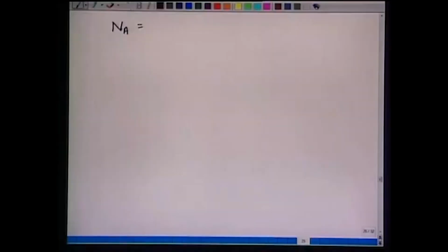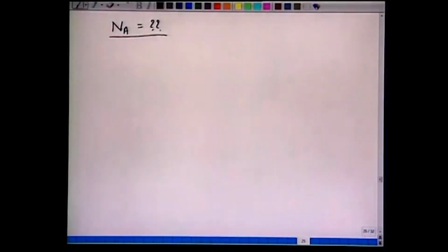Okay. And now, we can go back and still we can bring the expression for Na, diffusion flux. So, what is this Na now? That is a missing quantity. You recall this expression for Na still holds good. This Na consists of two components. One is bulk transport, Ya (Na plus Nb), and one is your diffusion equation, Fick's law, dAb dya over dz.